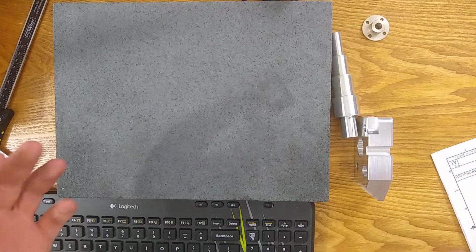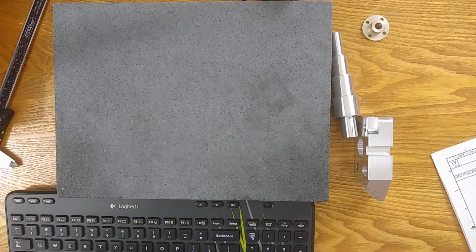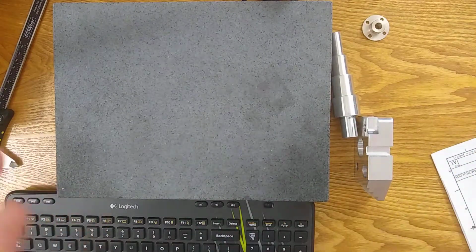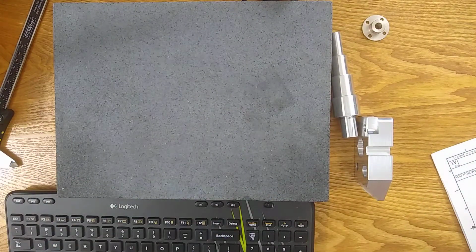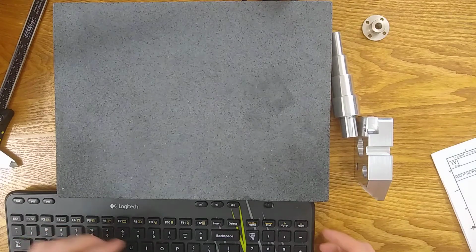As I said, whenever you see this frame, there are 12 or 14 GD&T symbols that might replace that position symbol. And there'll be different tolerances. You might have different datums and different modifiers. So it'll look a little different each time, but it'll still be shaped like a rectangle with certain sections. Symbol always goes first, then the tolerance, and then modifiers and datums.